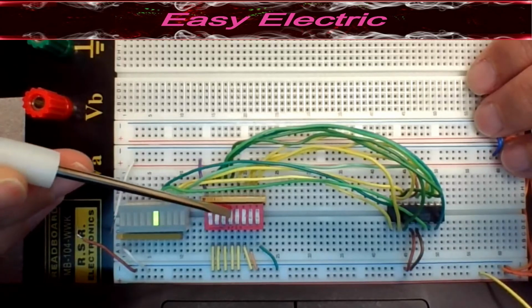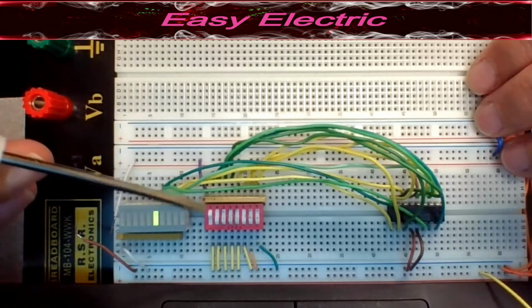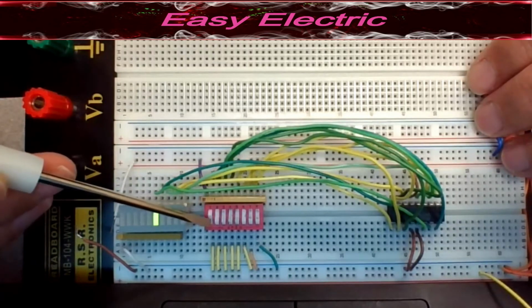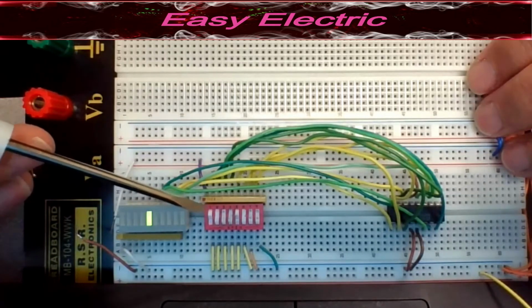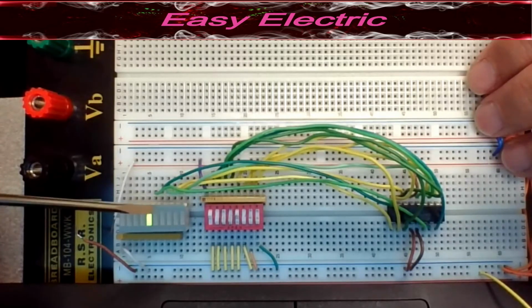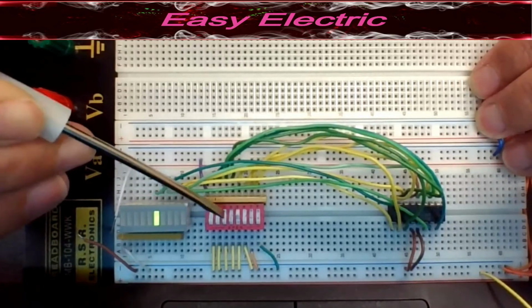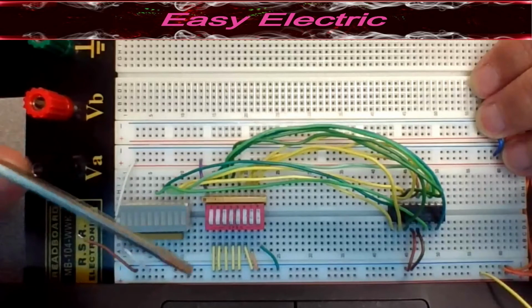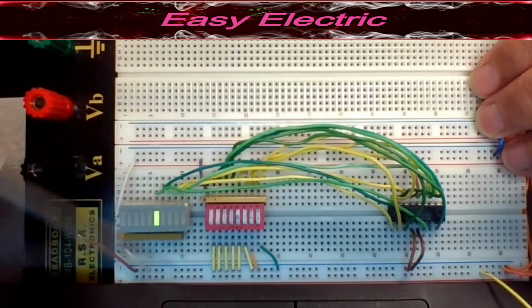If I add another 8, I should get 16, right? So that means it should jump here, right? That means C4 should be 1, the rest should be 0. Let's do that. A is 8. Let's put B as 8, A plus B is 16. As you can see, the rest are off and C4 is 1. So right now I have 1, 0, 0, 0, 0, which is definitely 16. Let's put these back to 0 and set A. Right now this should be 8, which is right.